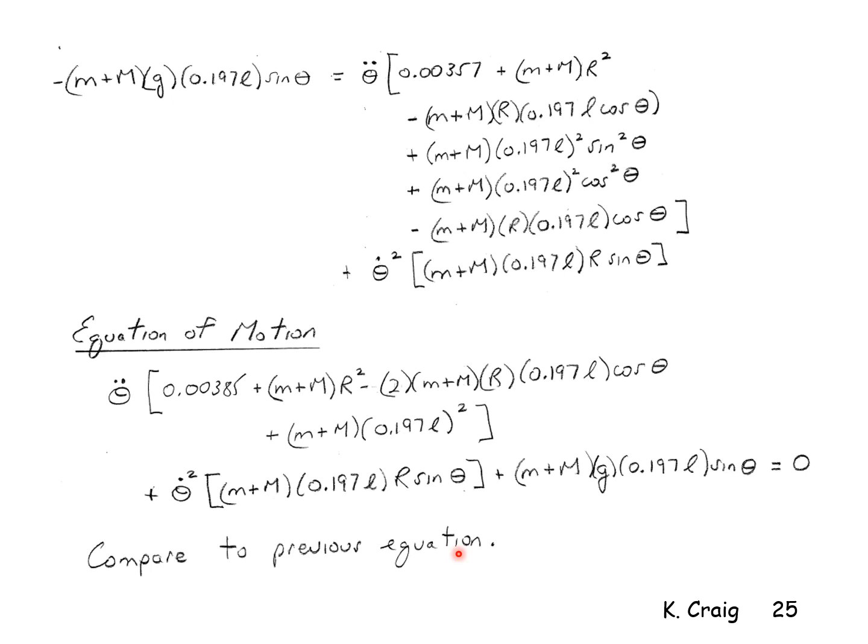Normally we don't want to do that because if I substitute in numbers and then the numbers change, I then have to redo the calculation. The longer we can retain the variable representation of our equation of motion without substituting numbers, the better off we are, because we can then see the relationships among different terms, and if we change parameter values, we don't have many more calculations to perform.